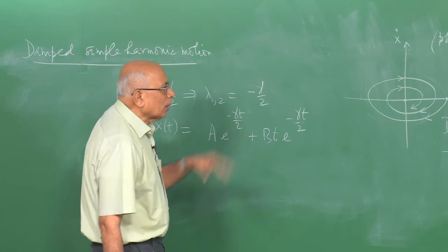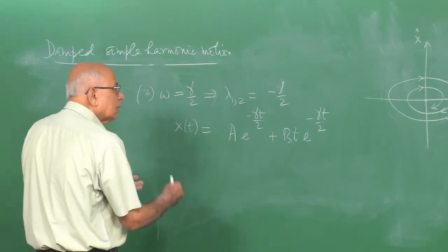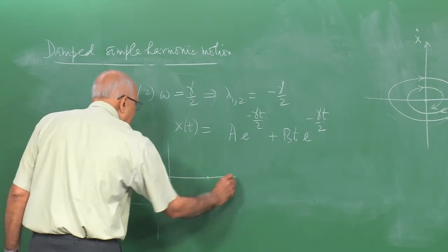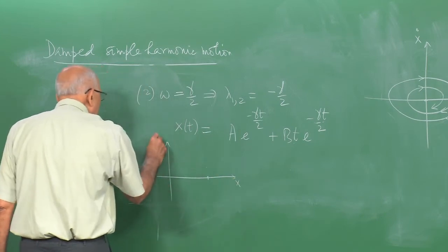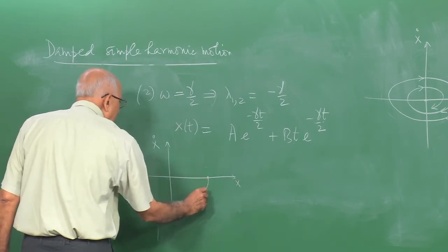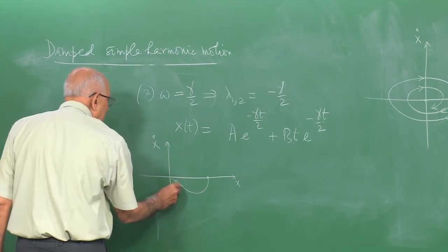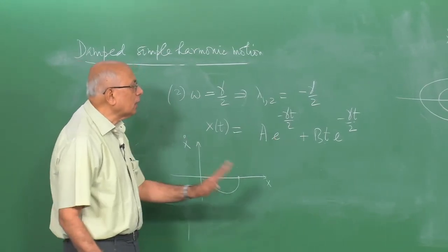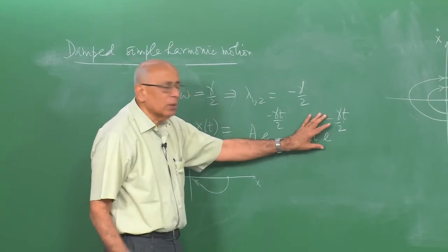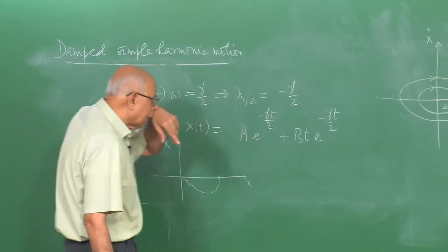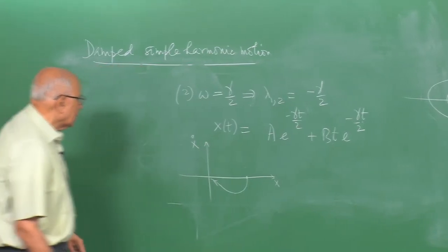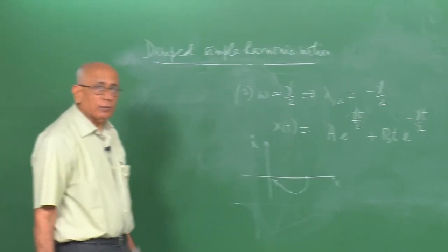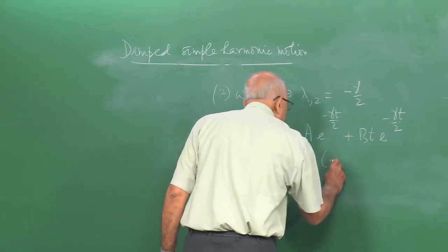So this is again an exponentially damped solution, and what happens here in the phase plane is simply that you have an approach, you start at x here, x dot here, it goes up trying to become a spiral and then slowly tends towards this here. It does not cross the x axis, never becomes negative, because for an initial condition such that A is positive and B is 0 it is always going to be just an exponential damped quantity which has got the same sign. So x remains positive, but x dot slowly tends towards 0, both of them exponentially fast. This is the critically damped case.